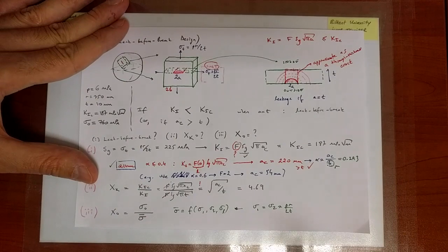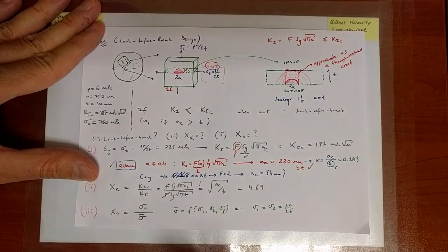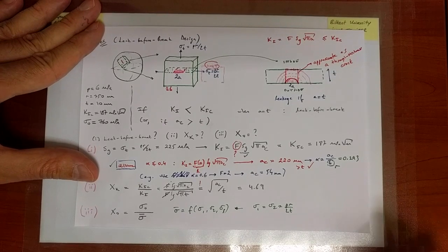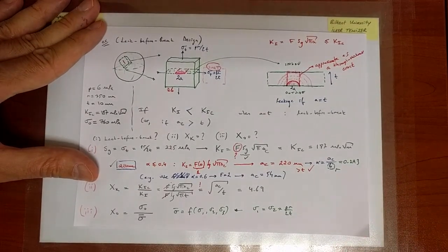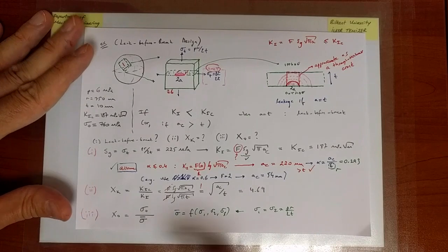materials. So when I talk about failure, I'm referring to what we discussed earlier, that is the limit of the region of elastic behavior. So we're checking the limit to elastic loading, and if we try to force the material beyond that limit, something will happen. If it's brittle, it will break apart. If it is ductile, it might yield. If it's significantly ductile, it yields a lot. If it's not so ductile, then it will not yield so much.